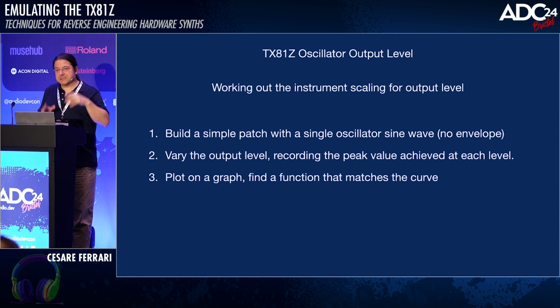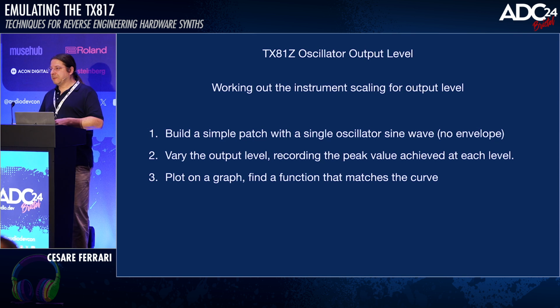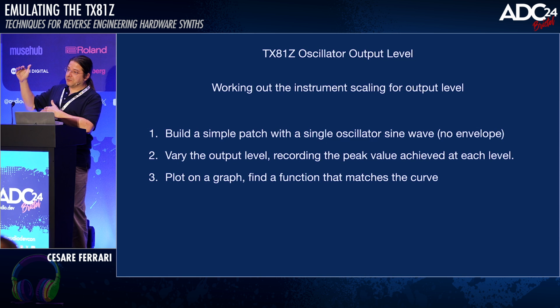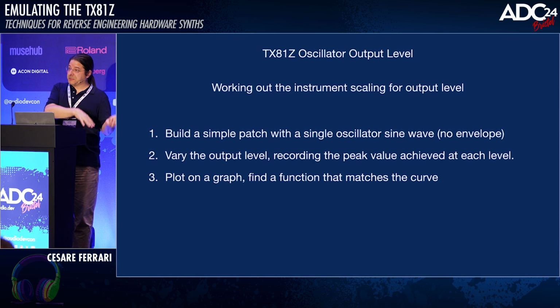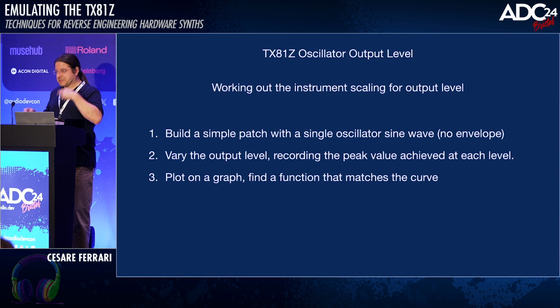So what we do is we write a little program in C major which says, send a note on, capture a bit of audio, what's the amplitude of it, convert it to decibels, output that, and does that in a loop. And then we just step through. If you could remotely control the parameter, I would write a program to generate and control it. In this case, though, it was just easy to hit the button and go, turn it down a bit, down a bit, down a bit, stick a few things into a spreadsheet, plot it on a graph.